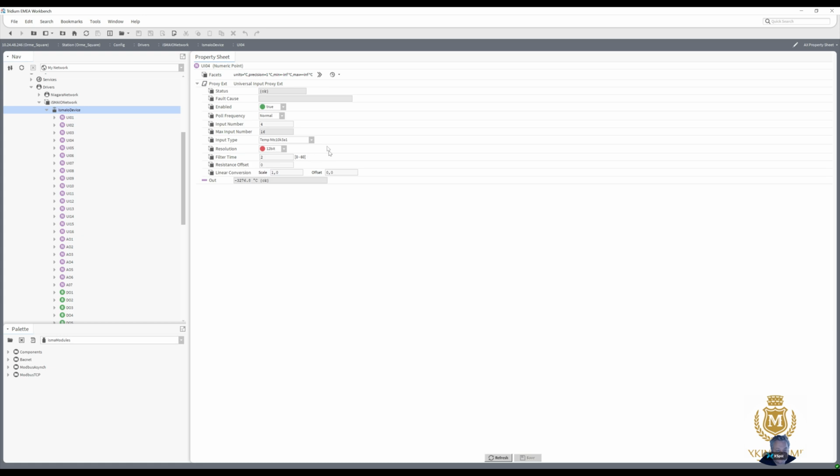And that's set to 10K 3A1. It'll drop down. You can have it voltage, current, digital, resistance, or then you've got your different temperature sensors that you can select, or a custom table. Well, we're just using 10K 3A1. Now if you use PT1000s, you change that 12-bit to 16-bit, but otherwise you just leave it at 12-bit on them all.